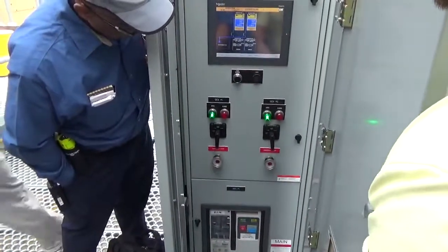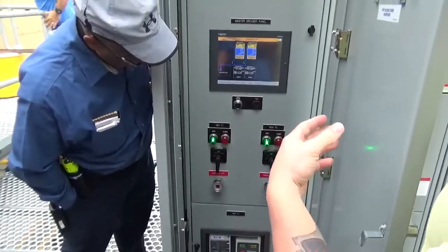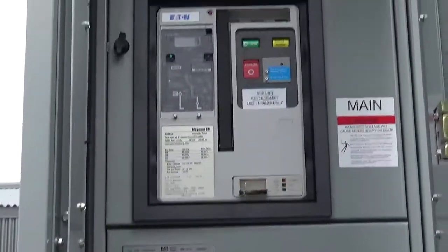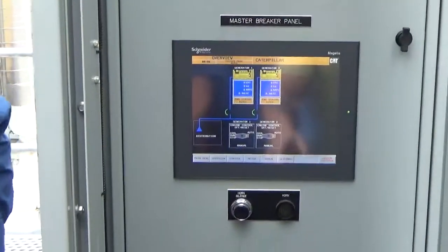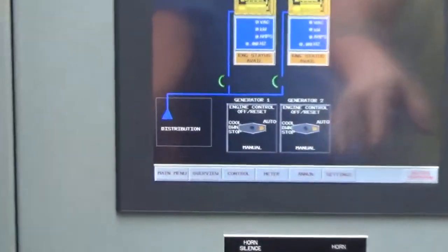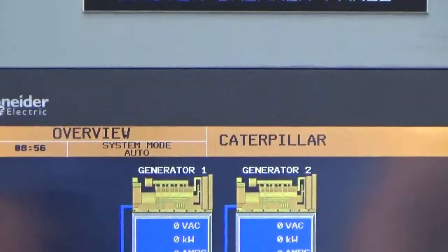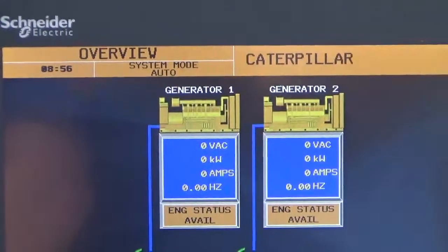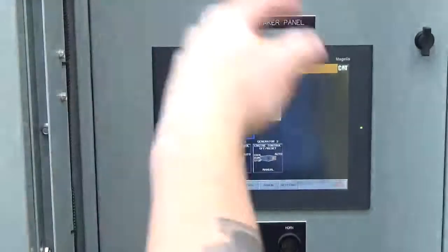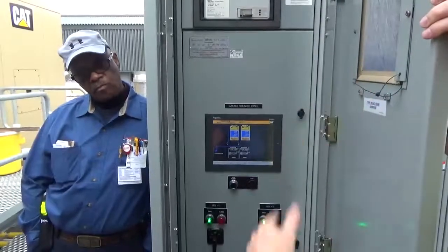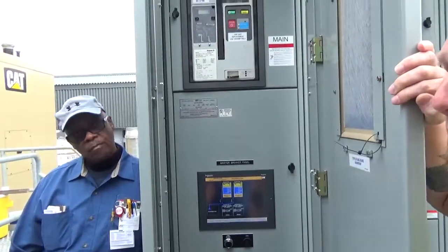All right. That's another shutdown fault, and there's a whole thing. He can explain to you how to do the generator shutdown reset for emergency stop. When you do an emergency stop here, it sends a signal out there to do the same thing. If I remember correctly, some systems are different, but this one: stop requested by switchgear. Yep. So then you'll have to go out there, reset it out there, and come back and reset it here. If you just stop it out there, you go out there and reset it, come back here, acknowledge, reset the alarm here, and you're good. Not a problem.